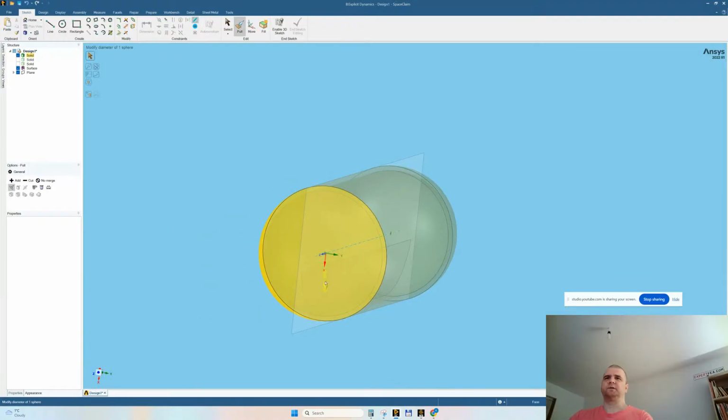Yeah, here. So I will, with control pressed, I'm selecting this surface with control pressed, revolve. I will click the sketch and tell it pull both sides, no merge, 180 degrees.